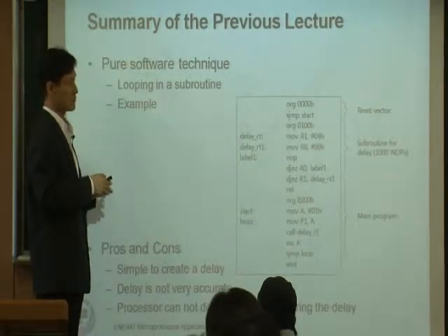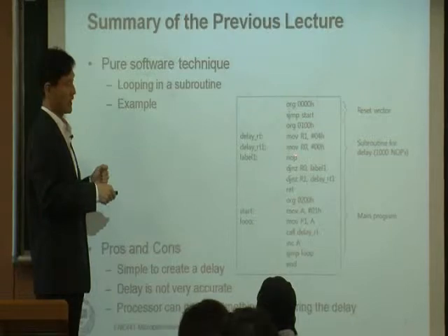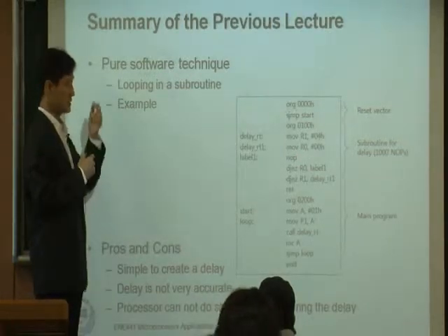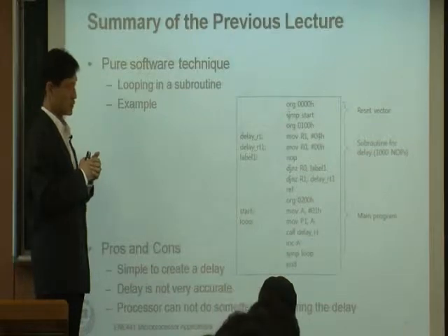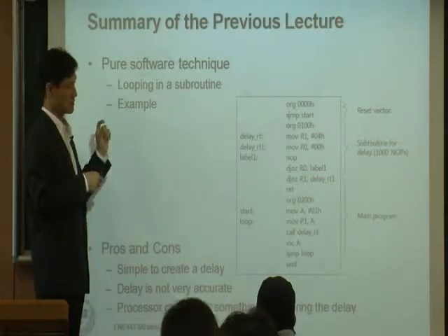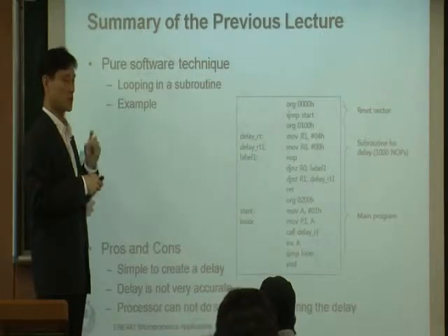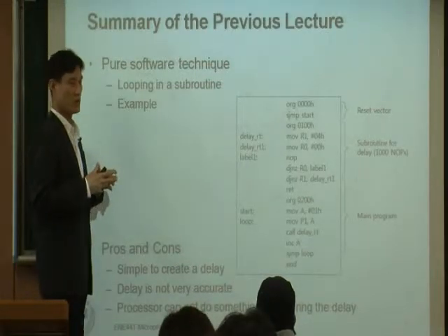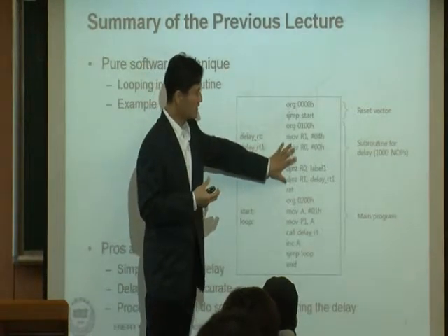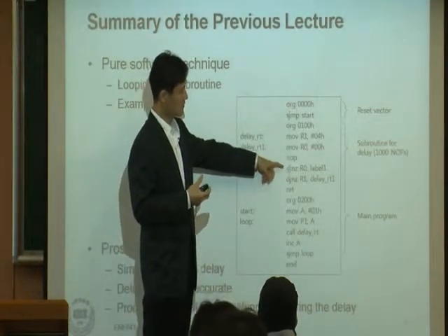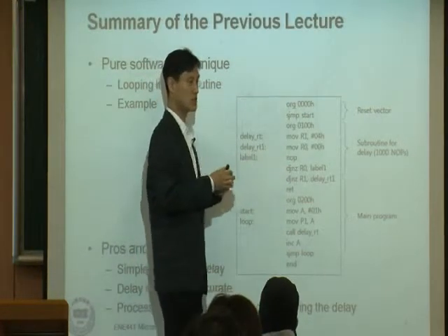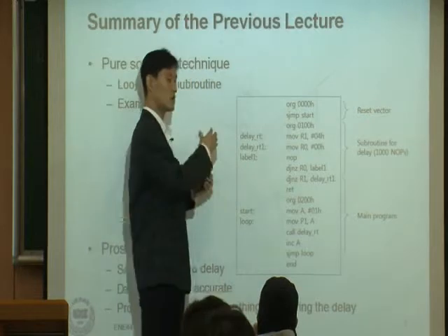But for our 8051 processor, NOP takes 1 cycle, and 1 cycle is probably 1 microsecond or something. I'm not sure, but that's not that short because our processor is pretty slow. Anyway, the delay here is based on NOP cycle, and how much time a NOP takes depends on hardware.